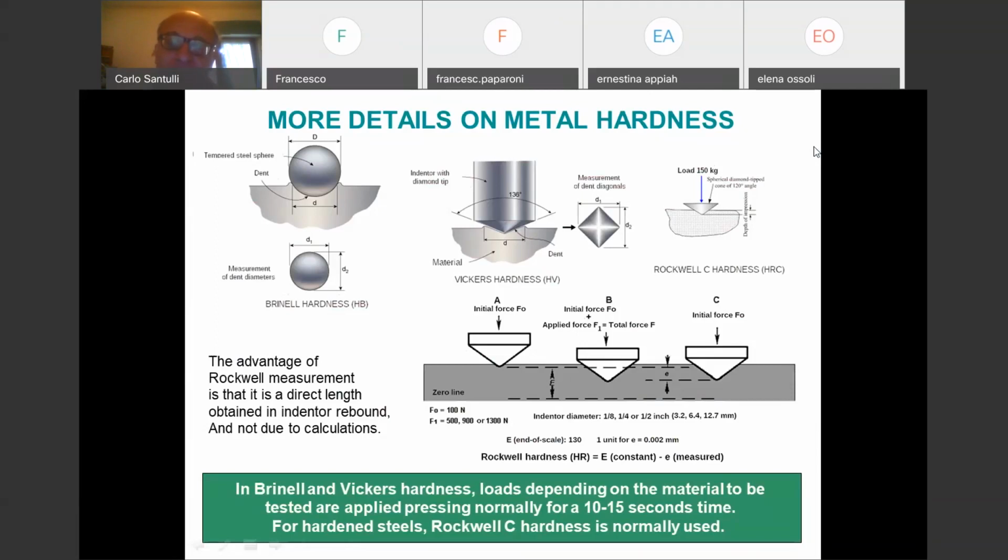Now there is a micrometer because you do that under the lens of a microscope, and therefore the measurement of the diagonals are now made semi-automatically, in the sense that it takes some measurement, but we need to verify if the measurements correspond to what we really see, because it's a question of pixels, and we need to decide if we are happy with that.